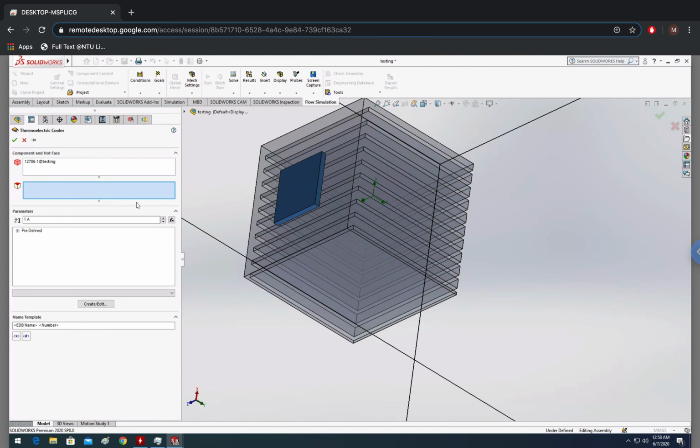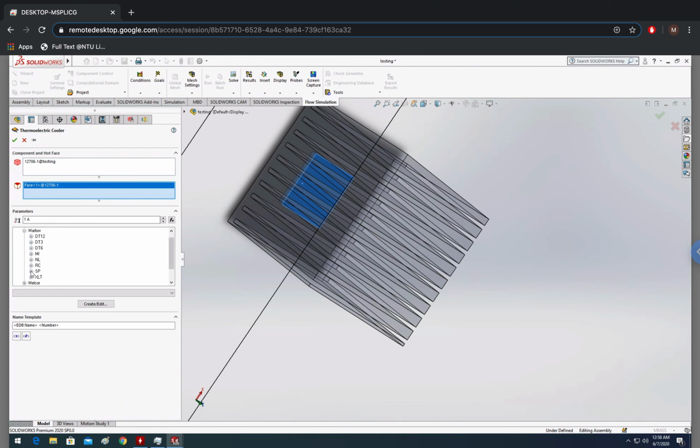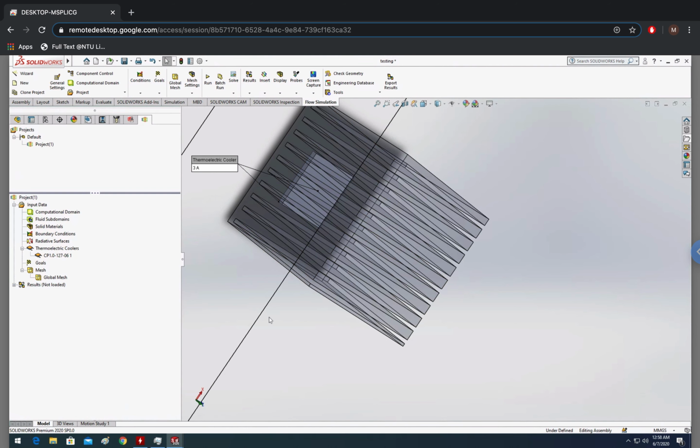So what's the Peltier? Maybe we just use, I don't know, maybe SP. Do they have one? Maybe they don't have. You can just use a normal single stage. I think I will use the CP model. Yeah, they have 12706. So maybe I just put 3 amp, the current for the Peltier. Okay, I think that's done.